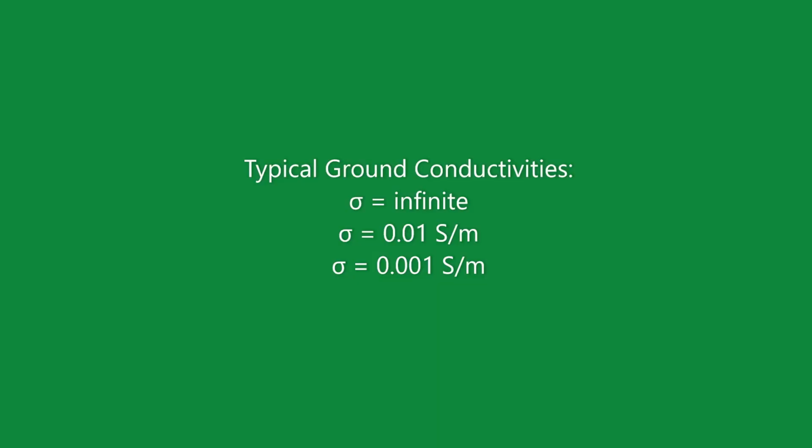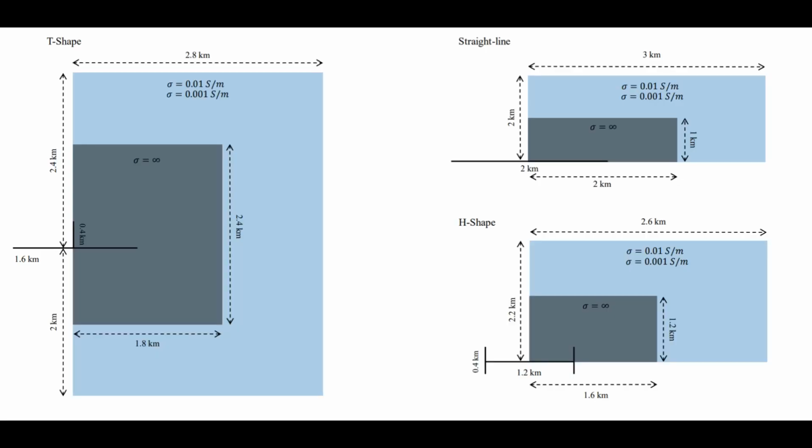We also choose 3 typical ground conductivities. It's also important to select appropriate striking areas depending on the symmetry of the test cases. The MTLE model is chosen with a 2000 meter attenuation constant. We also assume a return stroke speed of 120 meters per microsecond, and a channel-base current is set to be a double Heidler function. For the purpose of this project, it's important to highlight that all the Borghetti et al. results were obtained with an R sub k equal to 400 meters.